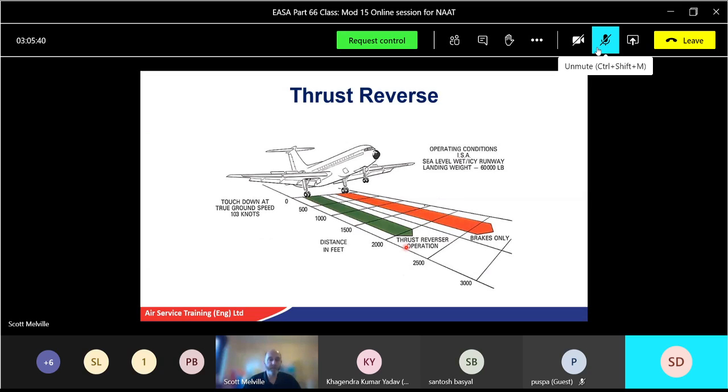What did primary do? Mixing with fuel and supporting combustion. Secondary? Complete combustion and shape the flame. Tertiary? Cut off the flame and reduce gas temperature. Yeah, good. It just cuts the flame. What it does is stop the tip of the flame touching the NGB, potentially burning it away.